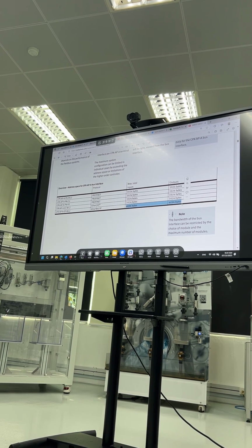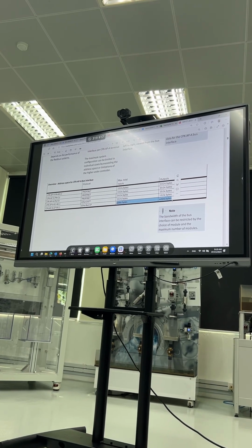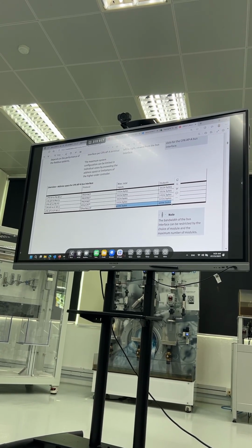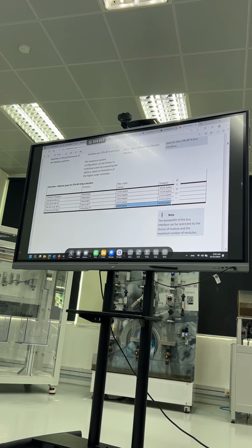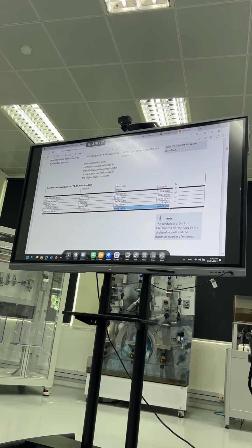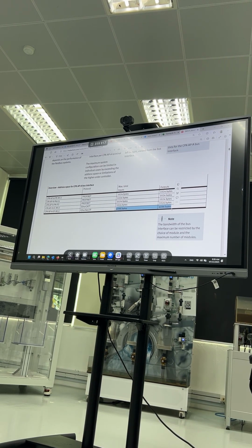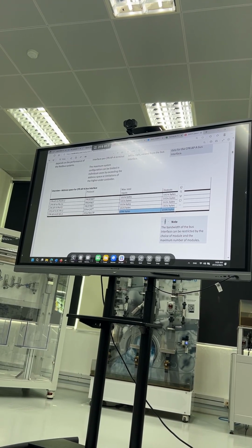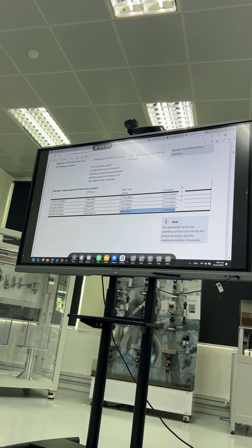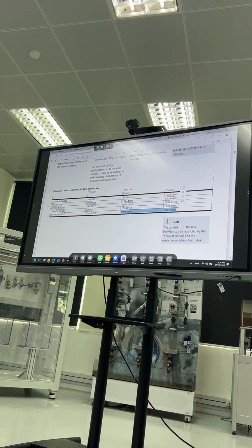Okay, so for example, if you are only connecting 79 digital inputs, you would use 79 times 2, which is 158 bytes. Okay, it's below this, so it's okay. But if we are using our IO-Link module, an IO-Link module can be up to 32 bytes per port. I'll just do the math. If you have like 50 or 60 IO-Link modules, it will probably be over this max total already, and then you cannot use it.